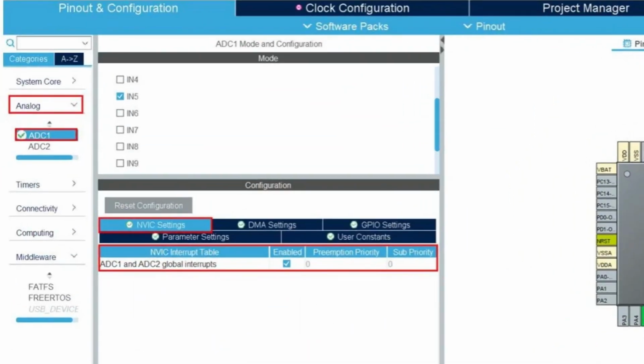So what's the better way? You mentioned interrupts. Exactly. A far more efficient approach is using interrupt mode. The setup is similar, but instead of starting with HAL_ADC_Start, you use a function like HAL_ADC_Start_IT. The IT stands for interrupt. This tells the ADC to start converting. But crucially, the CPU doesn't wait. It immediately continues executing other code in your application's main loop or goes to sleep if there's nothing else to do. So the CPU is free.